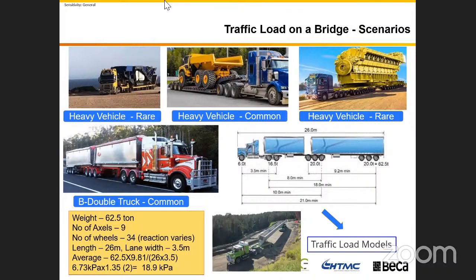Some of the trucks we are running on certain roads are way heavier than these normal B-doubles. And we test them before we allow them on the road, and that particular route is load tested. That's how we introduce them to the network. It takes some time to boil them down to the design standards. Botany Port, there are trucks running at 78 tons at the moment, and also at Botany Port they have asked to increase it to 100 tons, like super B-doubles. Okay, so that's how it is.